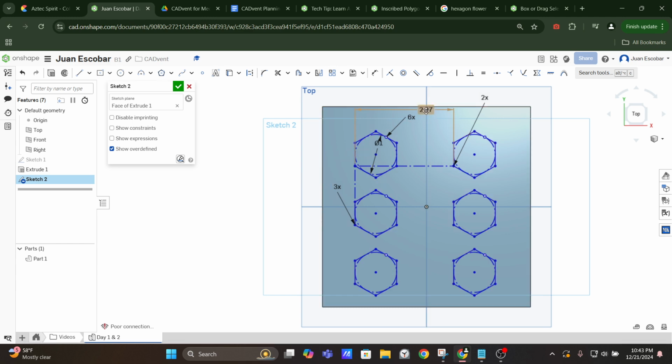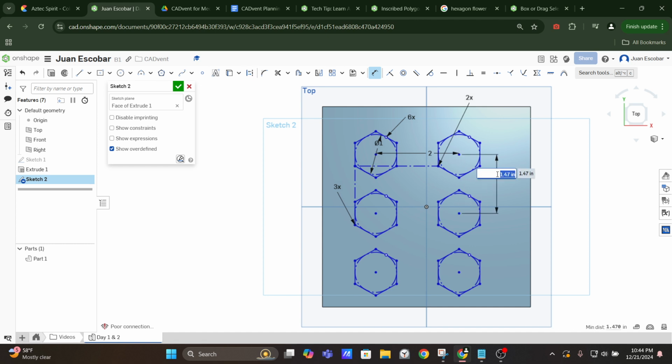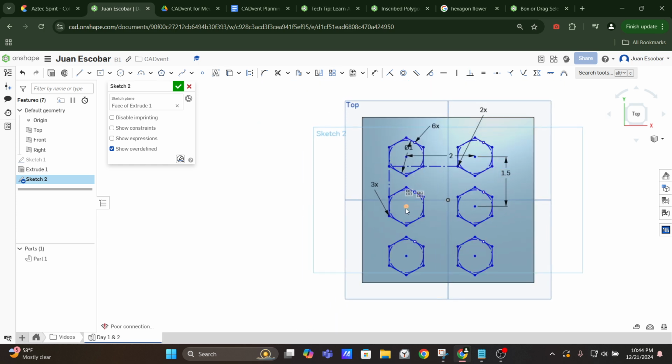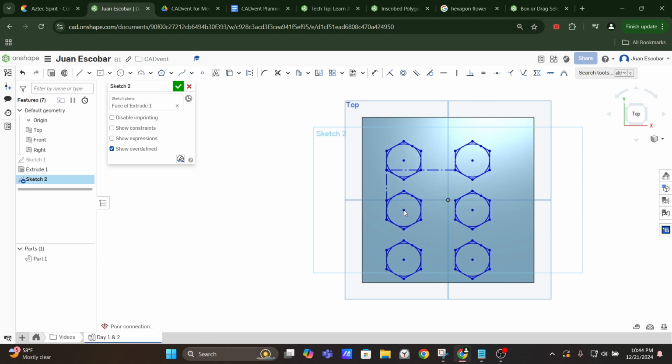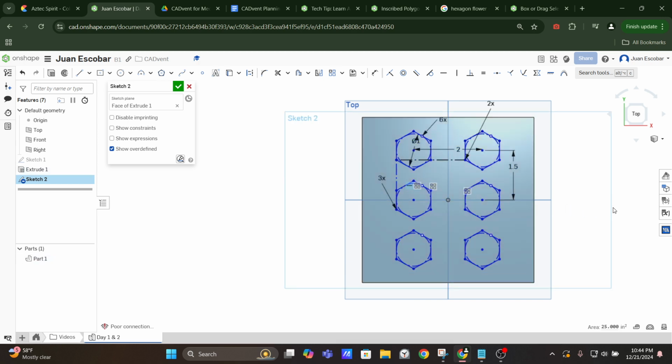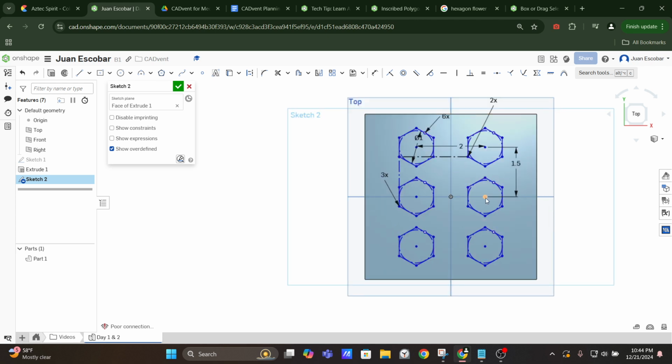We're going to get rid of them both because it's not doing what we want. With circles, it's going to be from center to center, and then you can just add dimensions. If you used this yesterday, congrats, you're cool. And if not, that's okay because we just covered it, and now you have a new tool that you know how to use. Look, I'm going to finish off this nice little part by making the center of this polygon, adding an auto constraint, and making it horizontal from the origin. Let's say I want this to be exactly centered. We could use some type of midpoint constraint, but we're not going to get overly complicated for now. I'm just going to add a dimension to the edge and make it 1.5 inches.